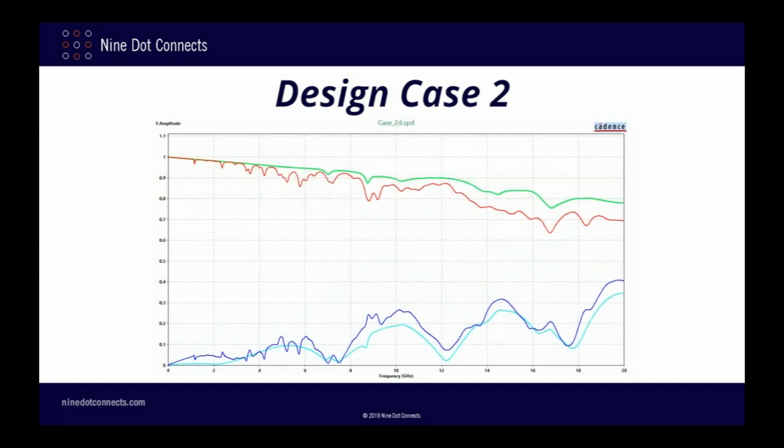Let's close out this section with one more slide comparing the uncoupled thin dielectric case with the ideal route of one signal layer and one reference plane layer. As we see, the general shapes of all of the curves are rather similar, which also helps give me a good feeling about the analysis. In fact, the transmitted power curves match almost exactly up to about 2 gigahertz, other than a few small resonant conditions.